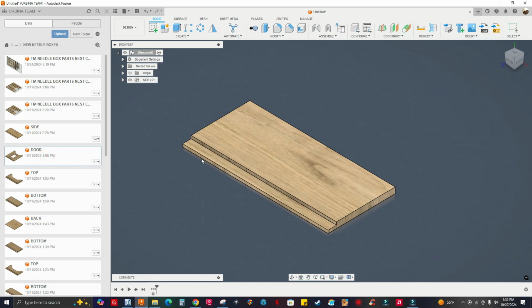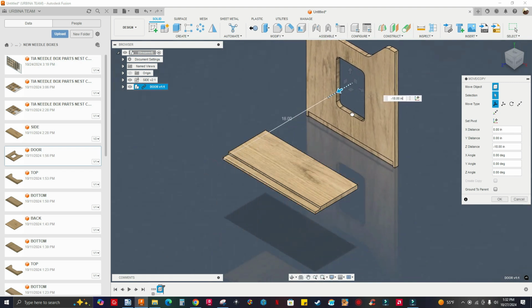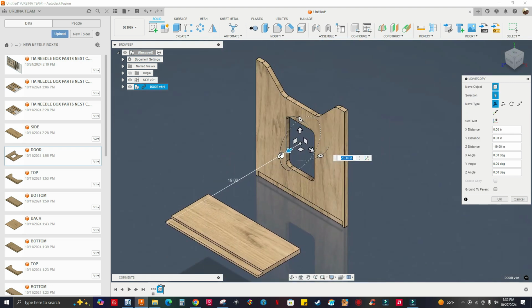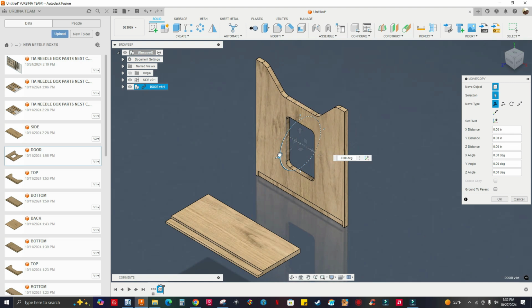Drag and drop, and I can bring it here, and then I'm not sure if I gotta lay it flat. I'll just leave it like that. Let's see if the Maples Pro plugin is gonna be able to nest and lay this flat. Okay, and let's see if it's gonna be able to rotate this part as well, because see the grain direction. All right, it has to follow this side component. So I'll just leave it like that, right? So let me click OK.